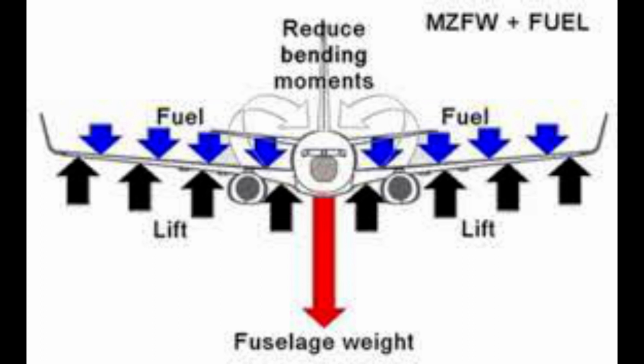Airplanes with tandem seating normally have a limitation requiring solo flight to be made from the front seat in some airplanes or the rear seat in others. Some of the smaller helicopters also require solo flight be made from a specific seat, either the right, left, or center. These seating limitations are noted by a placard, usually on the instrument panel, and they should be strictly followed.